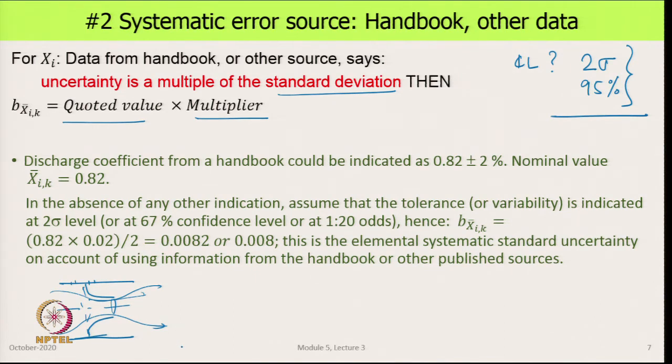From that pressure we calculate, using a formula, the flow rate, and that calculation is off from the real value by a constant called the discharge coefficient. So, we multiply that calculation by CD and we get the actual value of the flow rate.